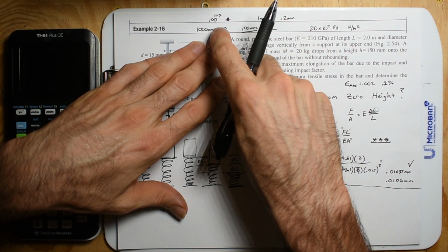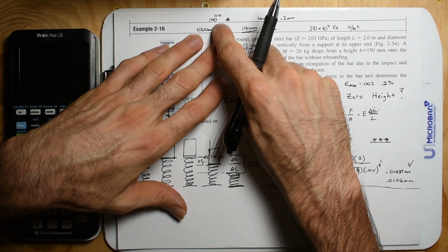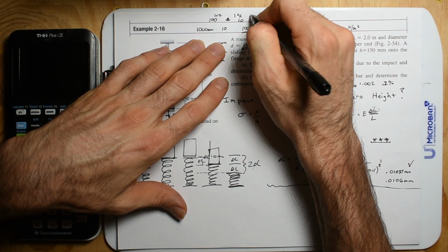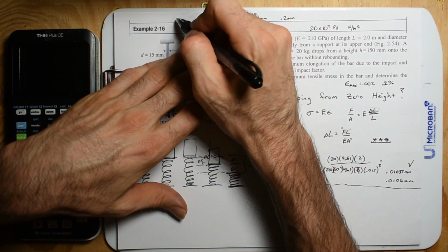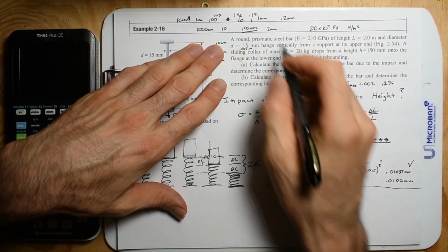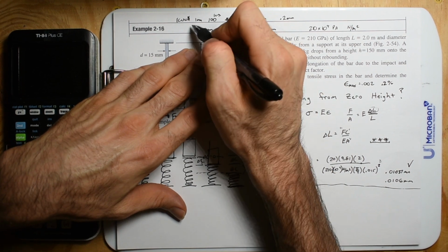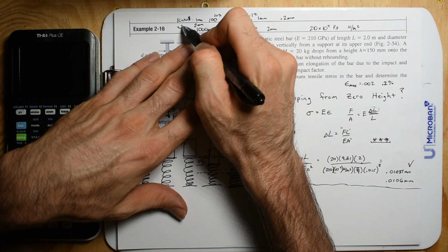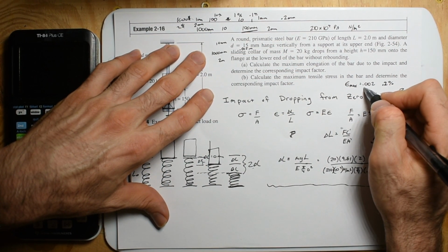But anyway, 10% of a $1,000 bill is going to be $100. What's 1% of that? That's where I wanted to go with this. That's $10. Now, what's 0.1%? Well, that's $1. So out of a $1,000 bill, 0.1% is $1, like 1 millimeter. But what's 0.2%? Well, that's going to be 2 millimeters, or for our case, it's going to be $2. Okay, hell yeah. So just getting used to strain is 0.002.